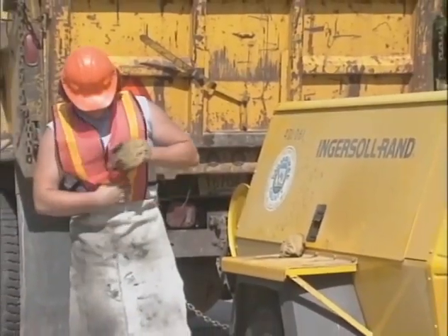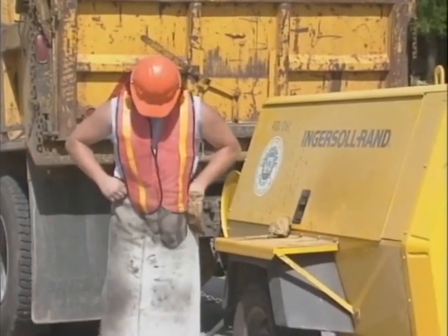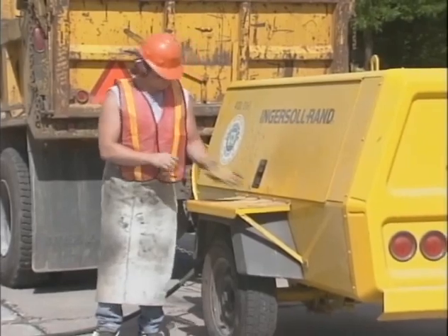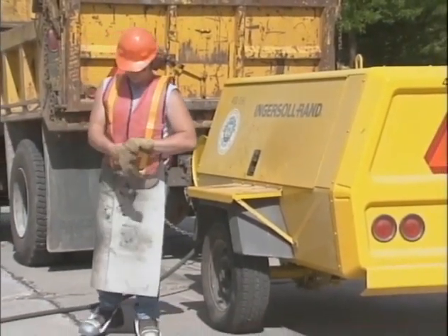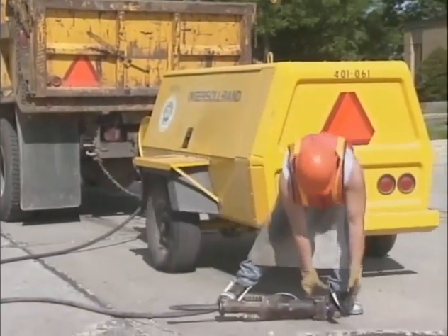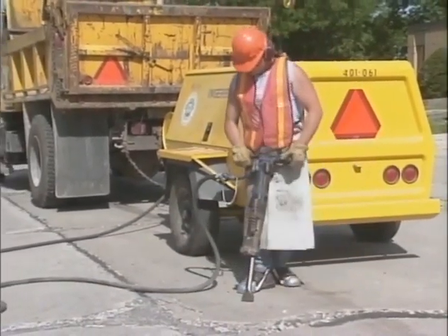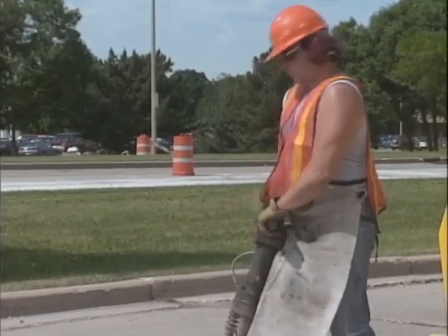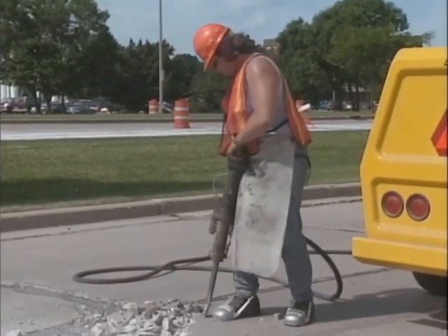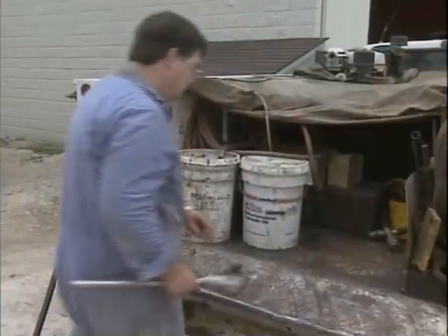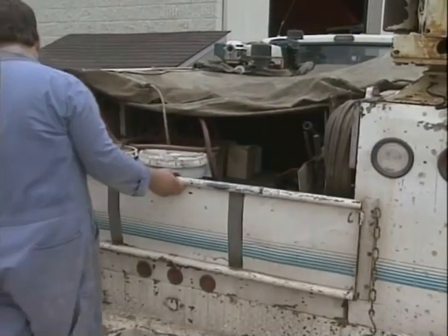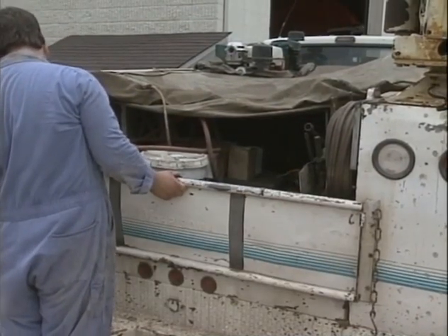Form good dress habits. Keep hands and clothing away from moving parts. Don't tempt fate with fumbling fingers, dangling ties, loose sleeves, or jewelry. Keep pockets free of all objects which could fall out and into machinery. Wear safety glasses at all times. Heavy parts. Handle tools and heavy parts sensibly, with regard for yourself and other persons. Lower items. Don't throw or drop them.